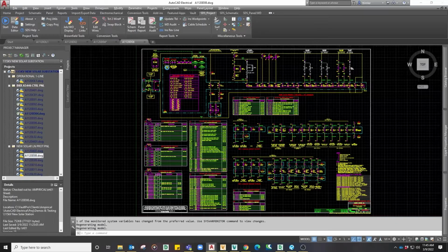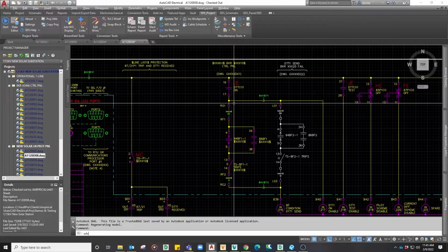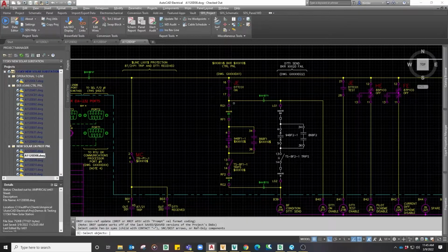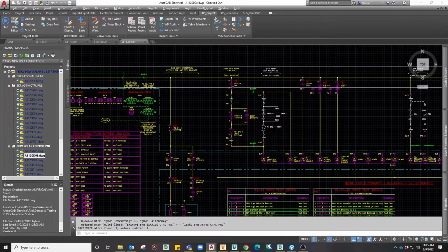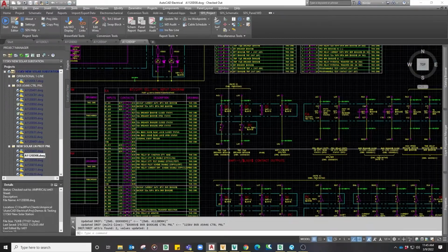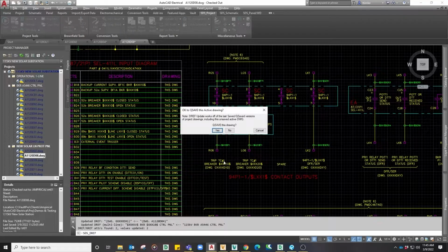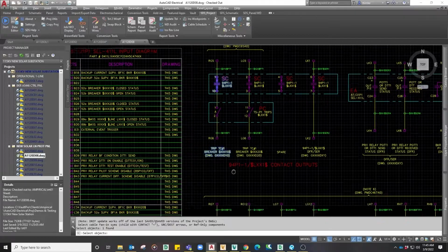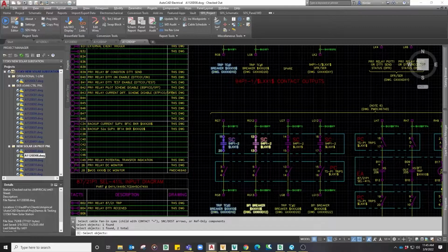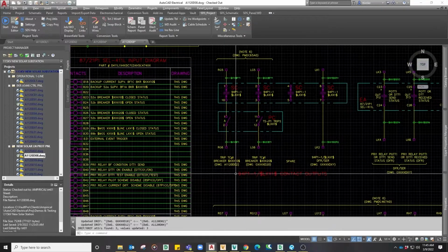And then finally, I'll go to the line panel. Run SDSDref again, and update the drawing cross-reference and the drawing circuit description. Now, these reference circuits also have drawing cross-references to the master symbols that they come from. So what I want to do here is run dref again and select all of the symbols that I used here to get their drawing cross-references to come in as well.